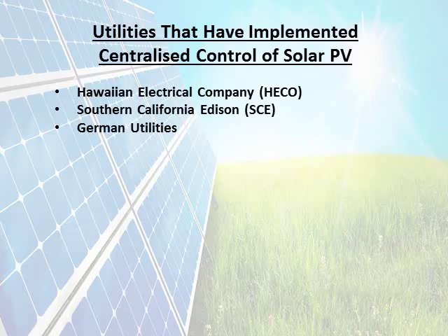The Hawaiian electrical company, HECO, was able to reprogram 800,000 microinverters in their network in one day. The purpose of this reprogramming was to have the microinverters ride through irregularities such as substandard AC voltages and frequencies, as opposed to simply disconnecting. HECO planned on reprogramming the microinverters to begin absorbing reactive power to assist in reducing overvoltages in the future.